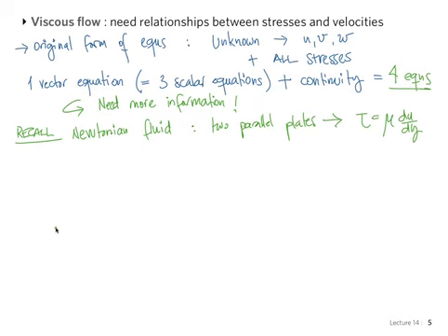It was all two-dimensional on the plane, infinite parallel plates, and the velocity only went in one direction. There was only a gradient in the y direction. The velocity was only in the x direction, so it was the u component of velocity. But what Newtonian fluid really means is that there is, in general, a linear relationship between the stresses and the velocity gradients.